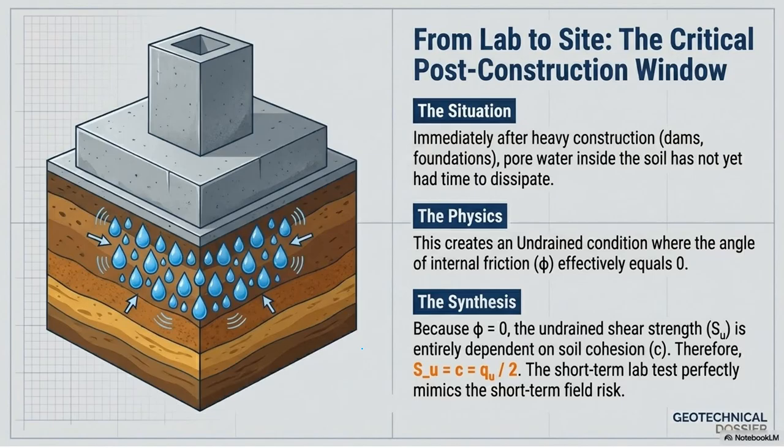So what do we mean by cohesion? It is the attraction between the soil particles, and they come closer when you start applying the load and the pore water starts escaping. So that is said to be soil cohesion. And this shearing strength is equal to cohesion, which is equal to compressive strength divided by 2, as mentioned here. So you can see that it is mentioned here.